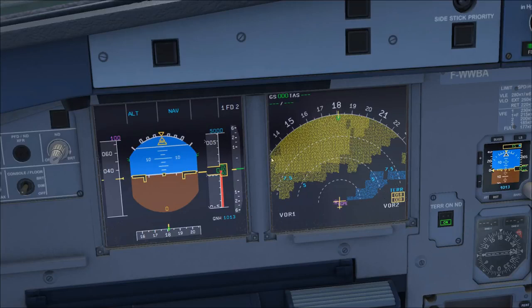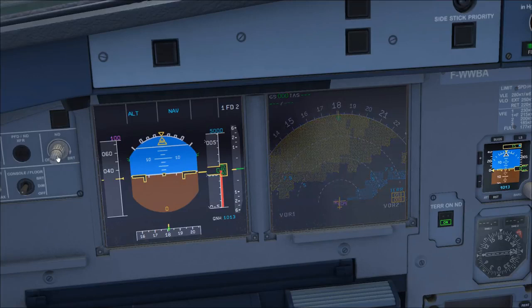Well, it also works for the terrain radar as well. So if I roll that down, you can see that the terrain overlay gets very dim and then very bright. So you control the overall screen display, or the screen brightness, with the smaller knob, and then either the weather or radar information with the larger knob there.